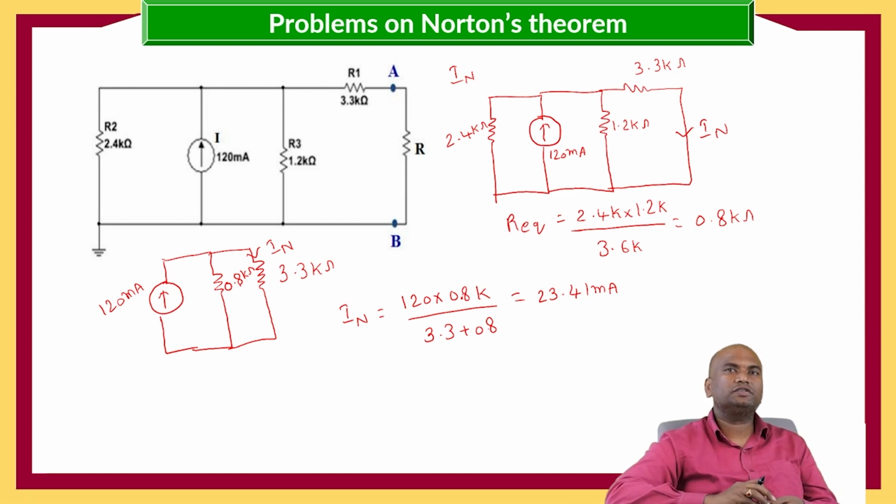Now we got the IN value, and in the same way we need to calculate the Norton's resistance by replacing the current source as open circuit, and the load resistance is also open circuit.